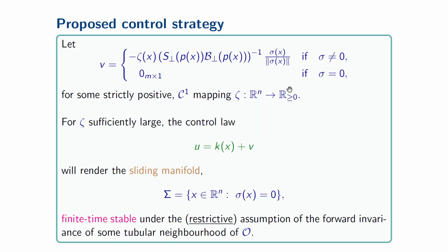Okay, now suppose we were able to solve and find such a switching function. How can we actually design such a robustifying feedback extension from it? Well, we can add to it a unit vector approach similar to what we did in the linear time invariant case, for instance. You can also use other strategies depending on your perturbations. Multivariable super twisting types of schemes might work as well if you have Lipschitz continuous rather than just bounded perturbations. But for bounded, we utilize this unit vector extension.